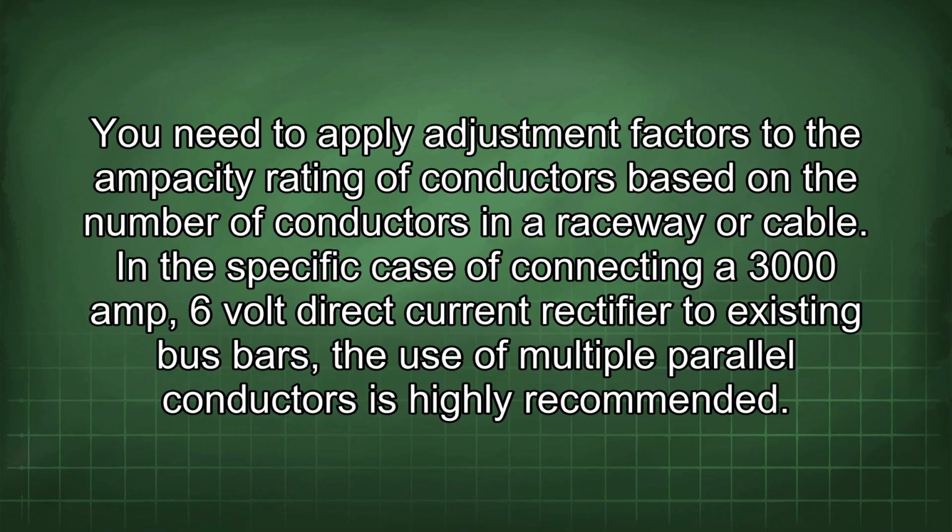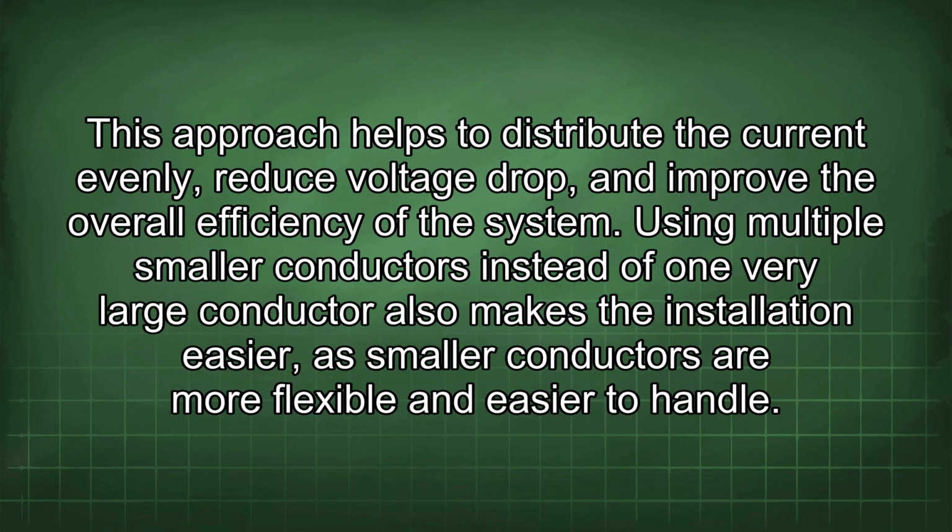the use of multiple parallel conductors is highly recommended. This approach helps to distribute the current evenly, reduce voltage drop, and improve the overall efficiency of the system. Using multiple smaller conductors instead of one very large conductor also makes the installation easier, as smaller conductors are more flexible and easier to handle.